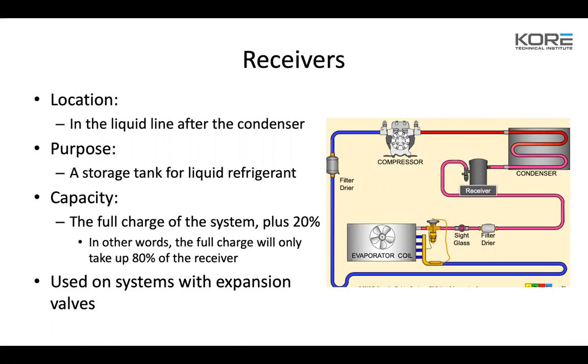And they're going to continue to rise as we have these really cold days, because that refrigerant's going to want to stay on the roof instead of get down to the case. And those valves are going to continue to hold back to keep that pressure up. And so we're going to need to have more refrigerant in the systems to be able to flow through the system like it should.